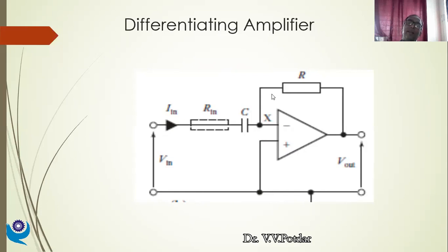Okay. So for the second loop, what will be the equation? What is the potential drop across the second circuit? It is V out, as no current is flowing across this OpAmp. The same current I is flowing through this resistance R. So what will be the equation for voltage output? Voltage output will be equal to I into R. So in that case, I will be equal to V out upon R.